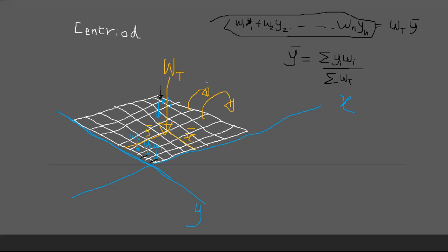So this W, right, can be written as, since this is an area, let's say the thickness is same, so W will be A times thickness times rho times g, right? Rho and g are constant for a particular element, right? Let's say the thickness is same for this plate element. So area times thickness gives you the volume.